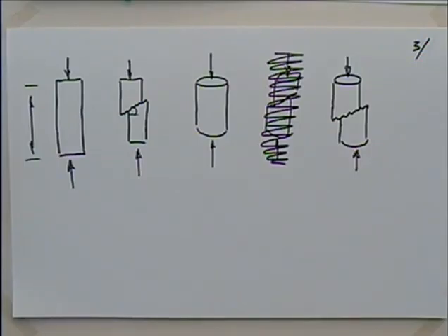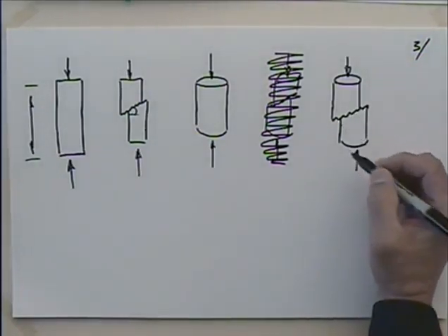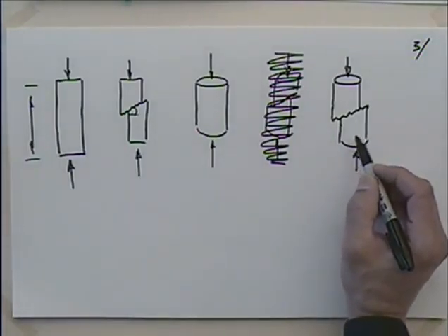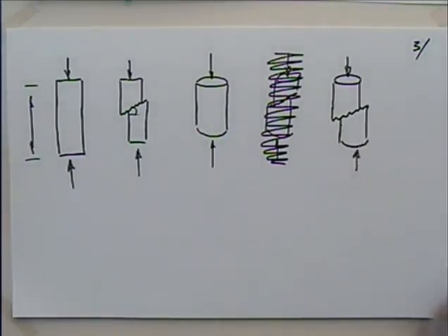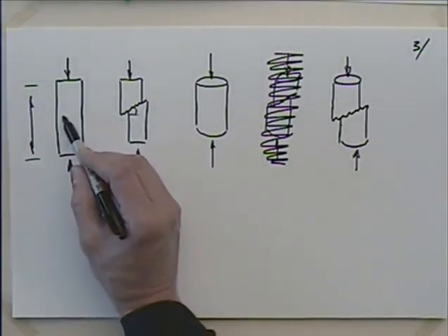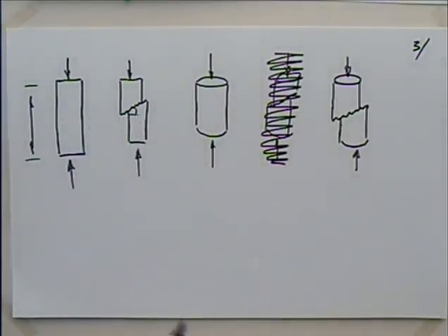And a lot of times these cracks and whatnot will end up at 45 degrees. It's because the concrete is probably very adept at handling compressive stresses, but maybe not so well in handling shear stresses. And those of you that go on to concrete structural will talk about putting some reinforcing bar in there or something to start to handle those. So things like this that we would think would fail in a compressive fashion actually fail in a shear fashion.